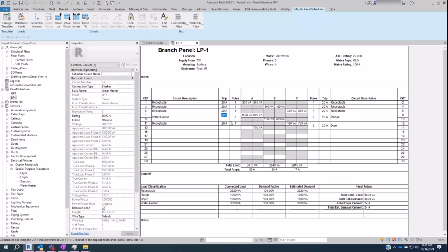Yes. It's always 125% of the actual MCA? Yes. If you don't have the MOCP from the manufacturer, that's how you do it, and that's per NEC. Multiply it times 125%, then go to the next size up breaker and be done with it.